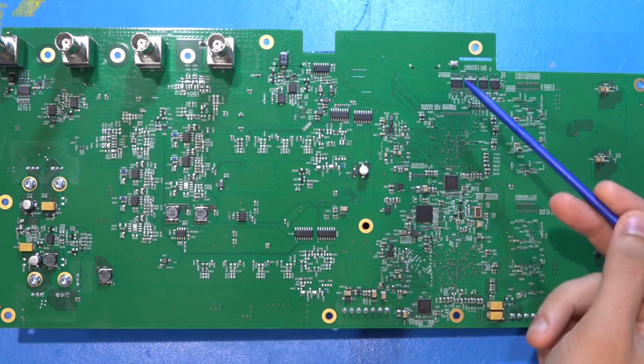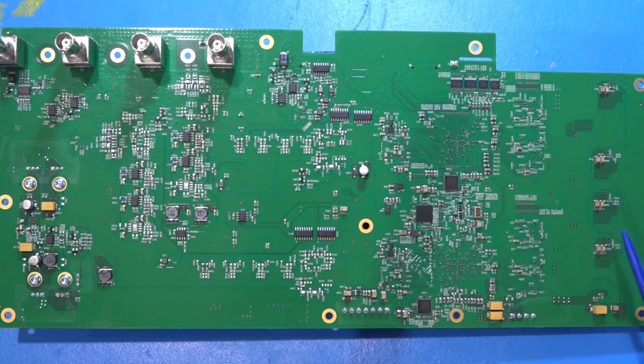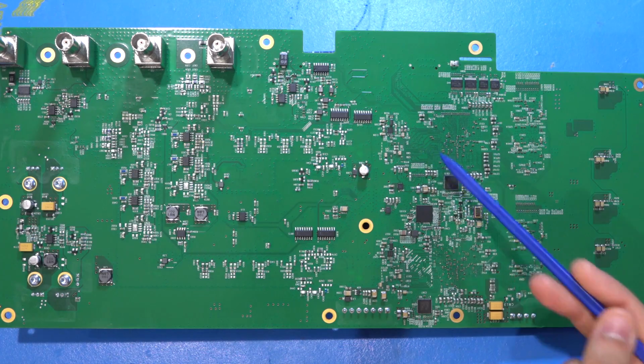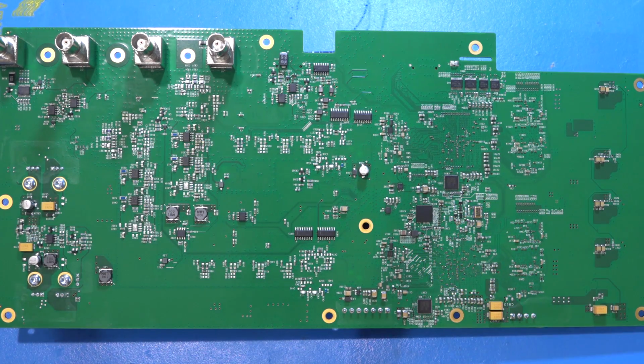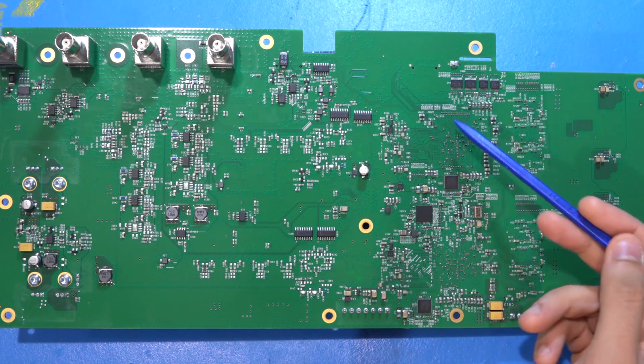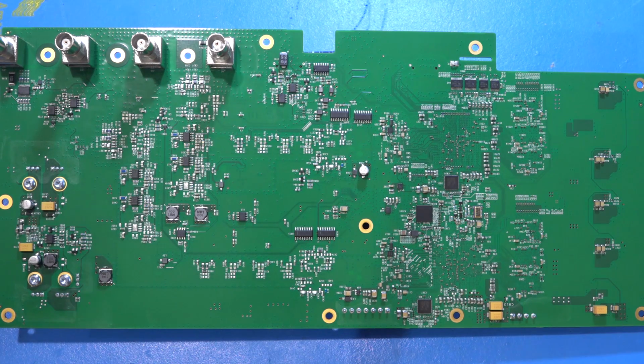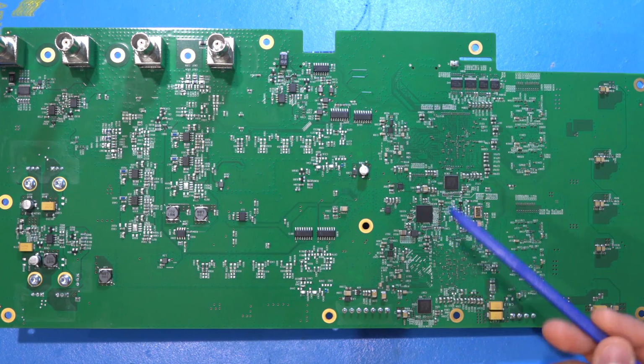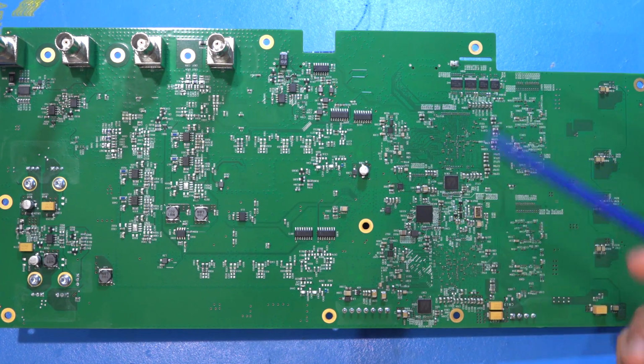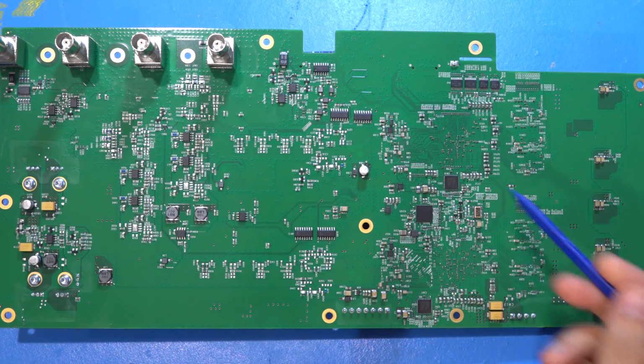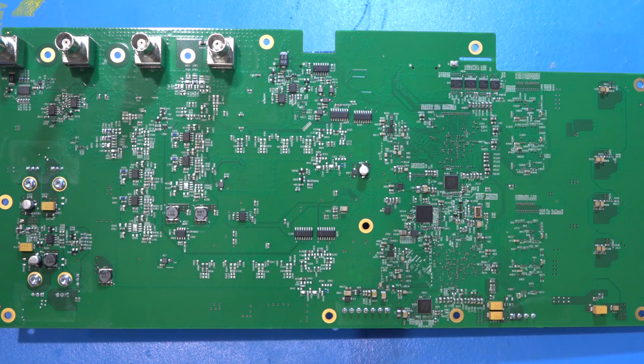Right over here is one of our connectors. You can see drivers responsible for that to do the communication with the back of the FPGAs. You can see the rest of the traces for the JESD interface. There's supposed to be 28 of them, I believe. 14 are on one side and 14 are on this side, carrying everything. And I think that's about it. It's a very nice board. Clearly, a lot of thought has been put into it. You're basically making an oscilloscope and an arbitrary waveform generator simultaneously in one unit, even though the oscilloscope doesn't need to be ultra high performance, just enough to give you a waveform representation.